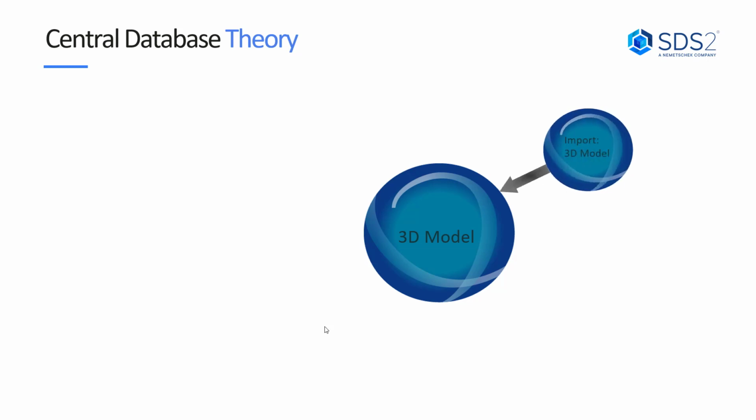If we wanted to, we could import 3D models into SDS2 that have been exported from other softwares. You can use file types such as IFC files or CIS2 files, and you can bring them into your SDS2 3D model as usable members.